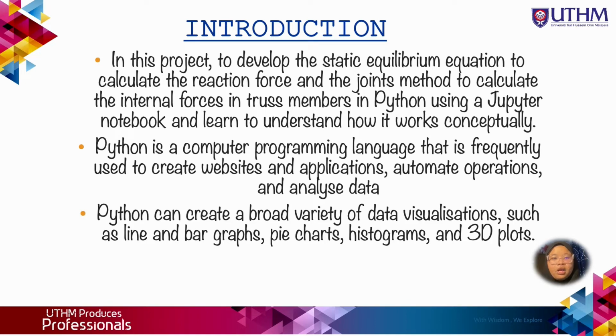To find the reaction force at the support, the creation of a free body diagram is the most important aspect of the solution approach for a rigid body equilibrium problem. Using the joint method, we must analyze the total of forces converging at a joint by resolving two equations of force equilibrium into orthogonal, or mutually perpendicular, directions.